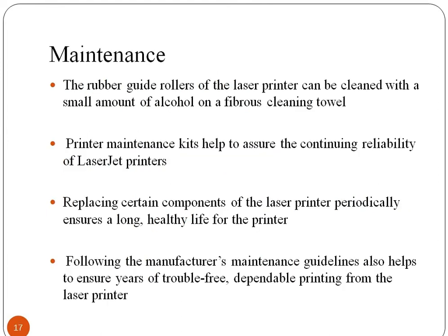Now, to maintain a laser printer, one should be aware of problems that occur in a printer. Now, what if you get an all white page? If nothing appears on the page at all, you might be completely out of toner. However, most modern laser printers will inform you of this fact and not simply quit producing output. This problem can also be the result of a broken transfer corona.